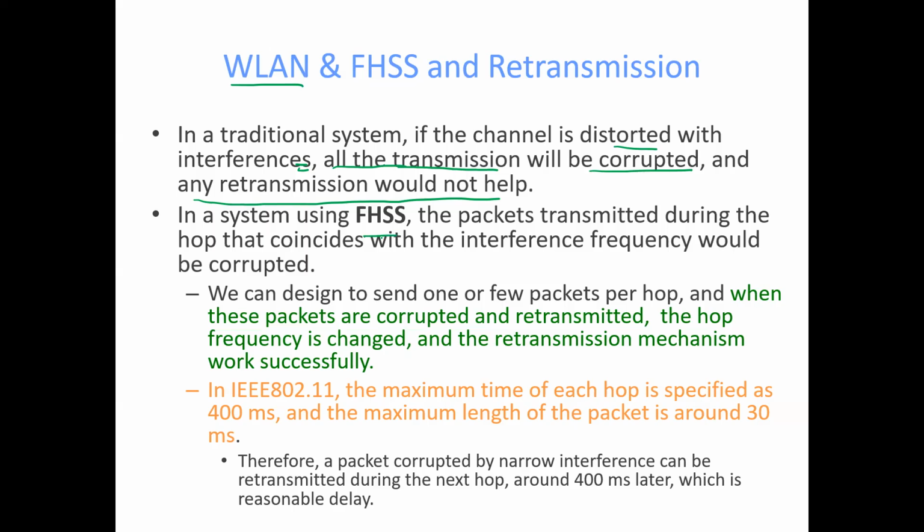But using frequency hopping, the packet transmitted during a hop that coincides with the interference frequency would be corrupted, but we can retransmit it. Okay, and this standard, which is Wi-Fi, uses this concept also. The maximum time for each hop is specified as 400 milliseconds.